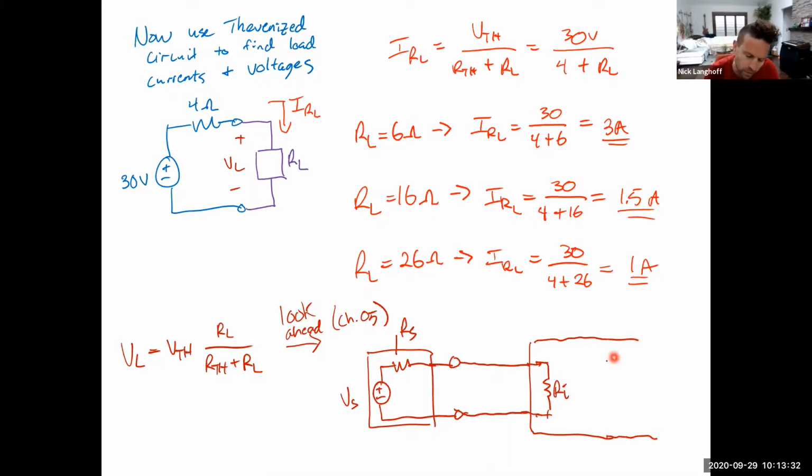This is a look ahead. Don't worry about this too much yet, but in these circuits, that amplifier will develop a voltage, let's say you had a voltage Vi here. This is going to give you a gain G times Vi, whatever the gain is. So if it's a gain of 10, the gain would be 10 volts per volt.